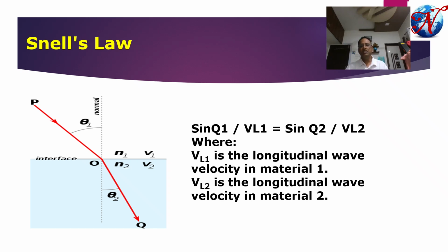But if the sound is traveling from one medium to another with a definite incident angle, say theta 1, other than 0 degrees, then there will be a mode conversion in medium 2. Some percentage of the incident longitudinal wave will be converted to a longitudinal wave in medium 2, and some percentage will be converted to a shear wave also. When the sound travels into medium 2, it creates another angle, which is known as the angle of refraction.